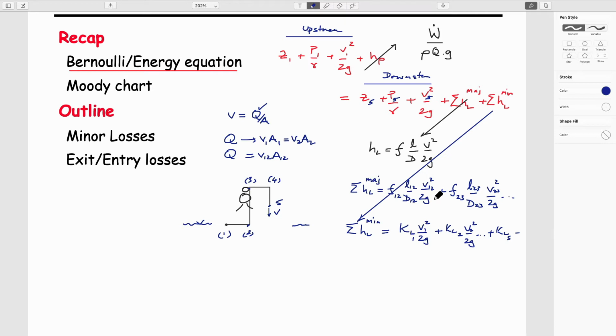And what you would want to know as a result of this, you would know that the pressure at point 5 is equal to 0 because it's atmospheric. You'd know the pressure at point 1 is equal to 0, or a small number, because it's underwater, but a trivial amount. So that's essentially atmospheric. You would know the height you want to be, a couple of meters, probably, between the nozzle that's attached.